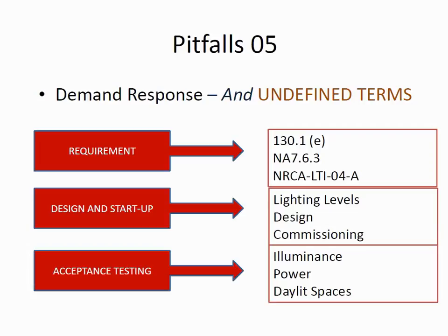We are going to examine my least favorite type of lighting control, automatic demand response. First, we'll examine some of the undefined terms used in describing the power illumination reduction requirements for this type of control.